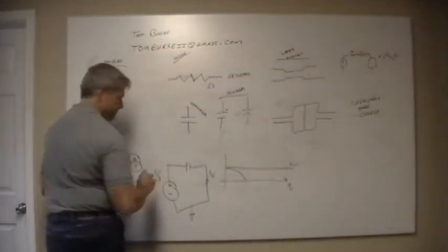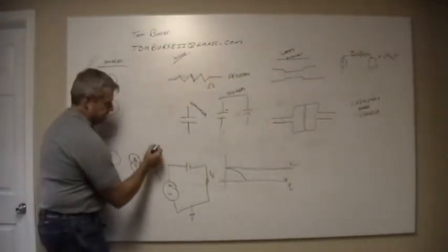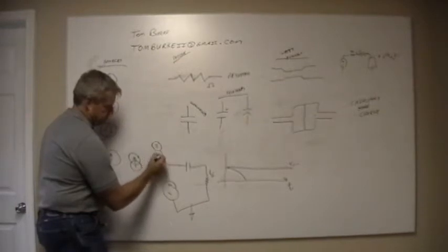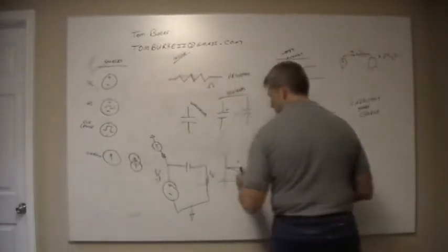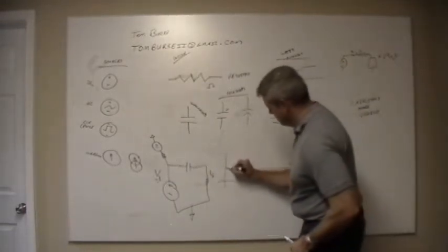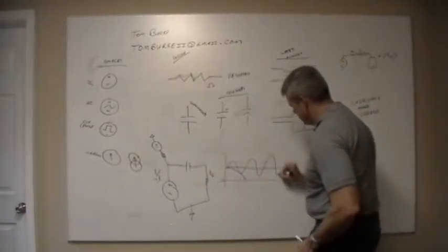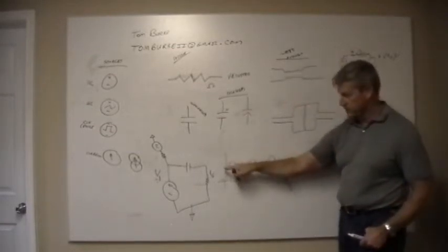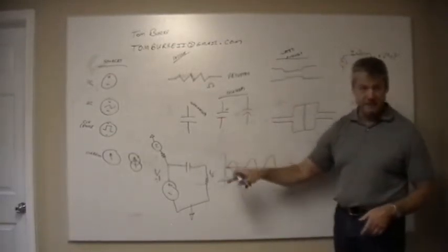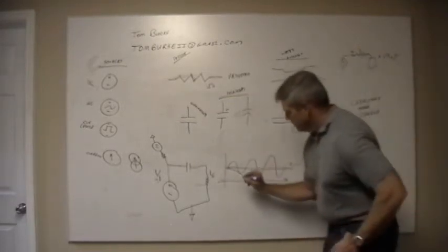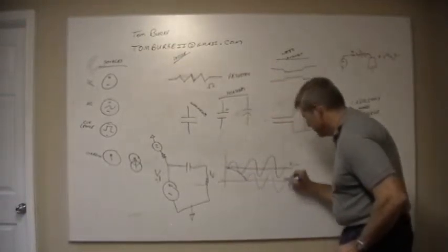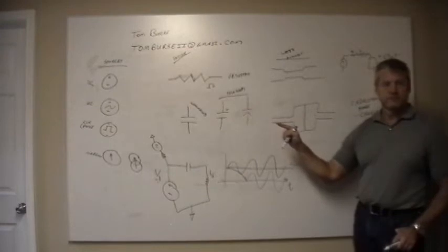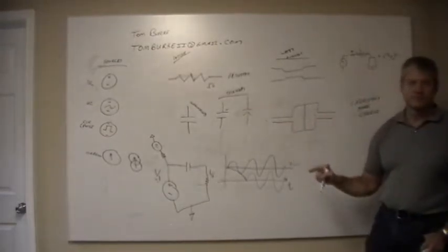But now if I have, let's say, an AC circuit on here through some sort of a resistor back to ground. Now if I look on the V1 side, I've got this, right? I've got the AC circuit feeding in on top of DC because the voltages are going to add, they're in series. What I'll see on the other side is, once this charges up, I took the DC out of it. It lets me isolate DC. That's useful.